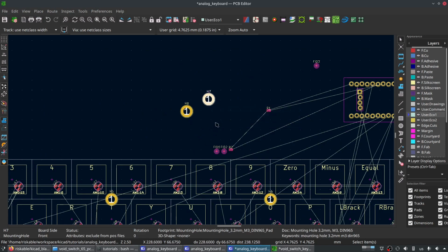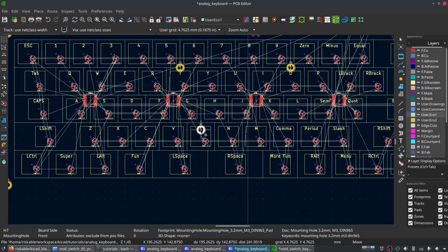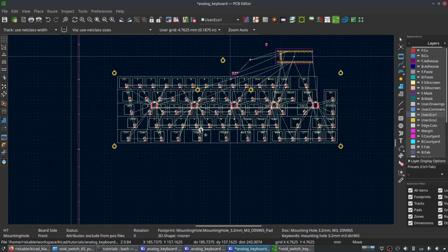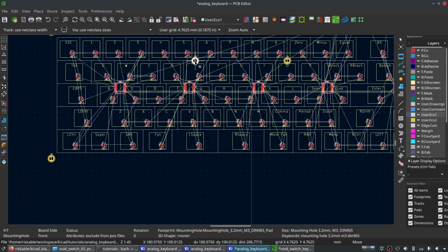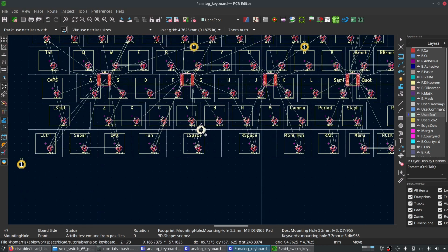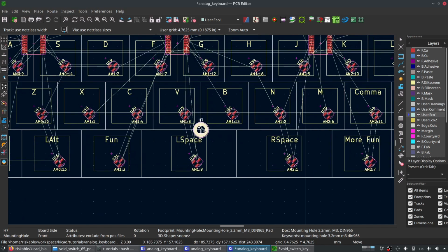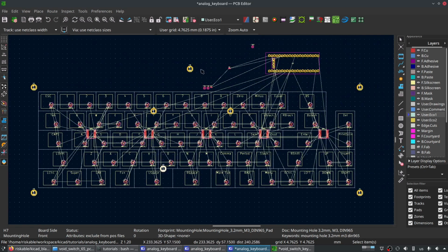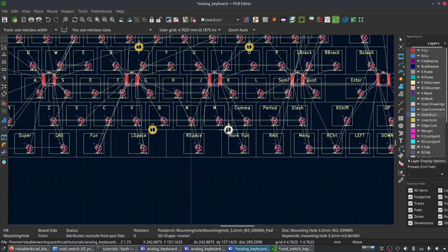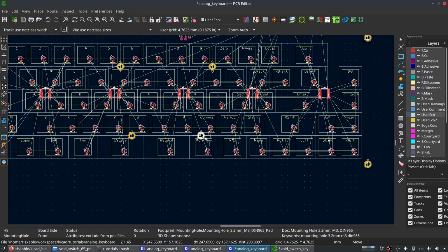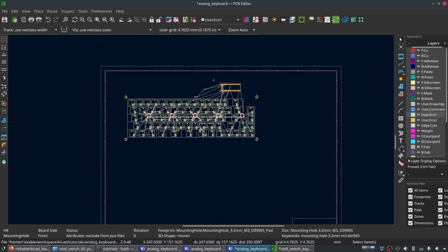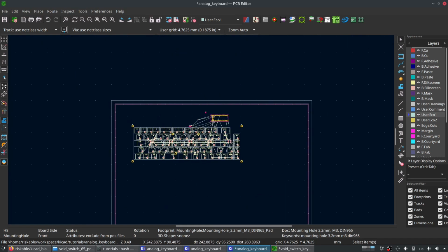Now let's take 7 rather, and space bars usually have plenty of space around them. So I'll just move this one. It's kind of annoying that we can't keep them lined up because it'd be too close to that Hall effect sensor. So I'll move it over just a smidge. Yeah, it's kind of close. Go right there. That's fine. It doesn't matter that much. There's plenty of room in the case for M3 screws. And for this one, we'll do the same thing right around here. Yeah, that's good enough.